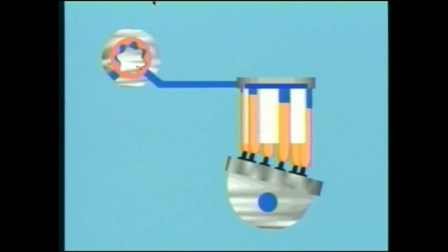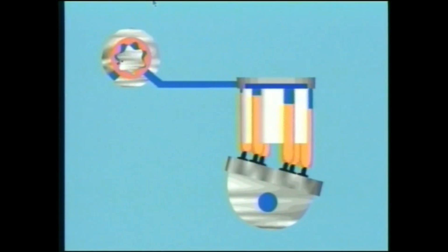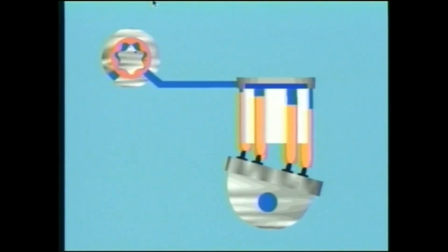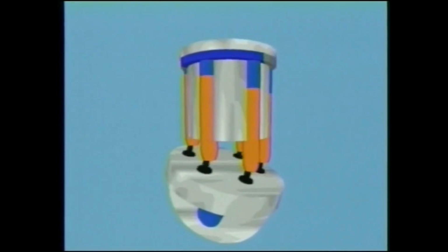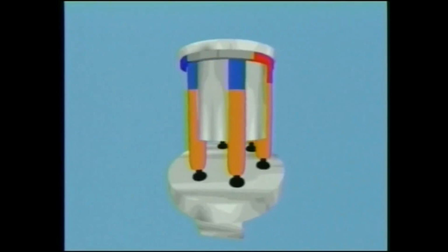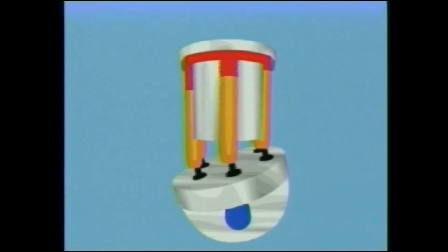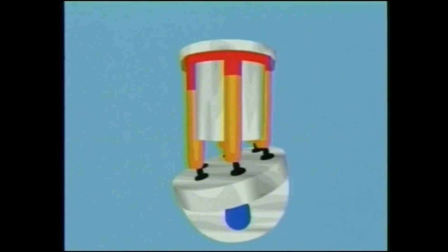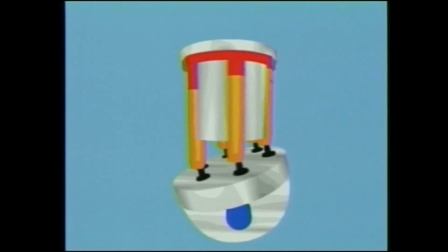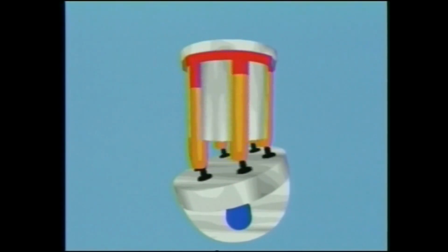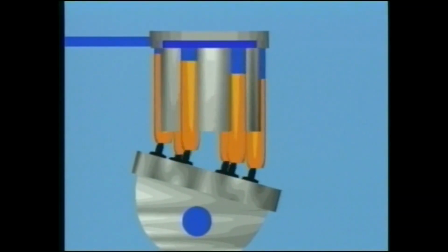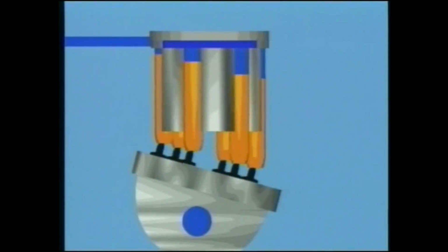The pressurized oil then flows through a one-way check valve or charge port to fill the cylinders. As the pump rotates and the pistons reach the bottom of their strokes, the inlet check valve or inlet port closes. As the pistons rise, they push the oil out the outlet check valve or outlet port. The cycle is repeated as the piston cylinders again fill with oil.